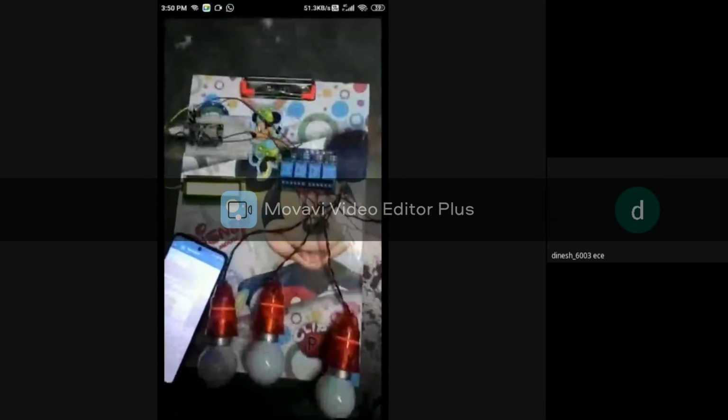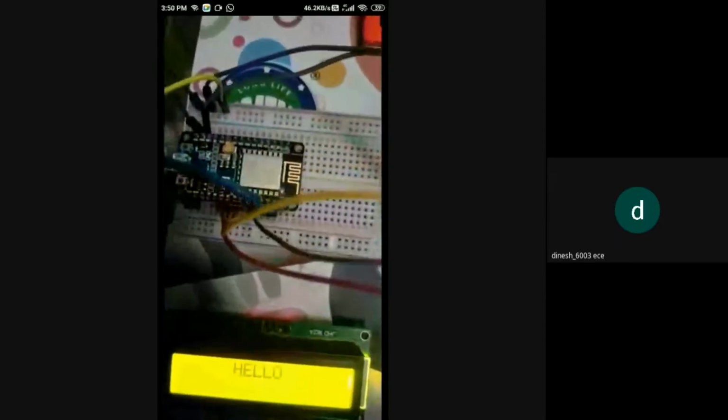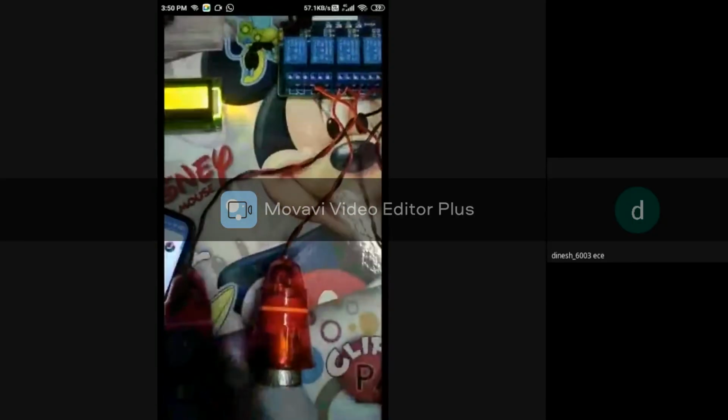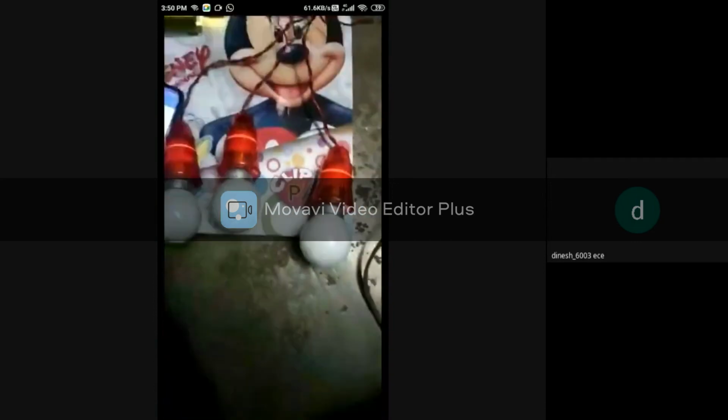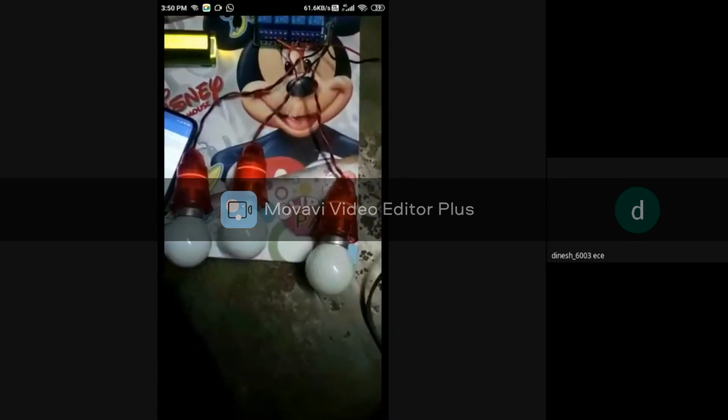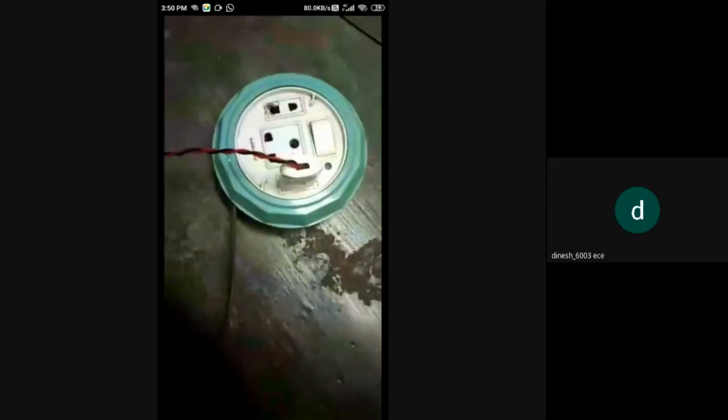Our project is about a home automation system, where we have 3 modules. One is the ESP8266, which is a controller Wi-Fi modem, another is the relay module, where we have 4-channel relays, and the third is the LCD, which is connected by the I2C protocol. Now we have 3 lights, connected to a black box with the power supply.